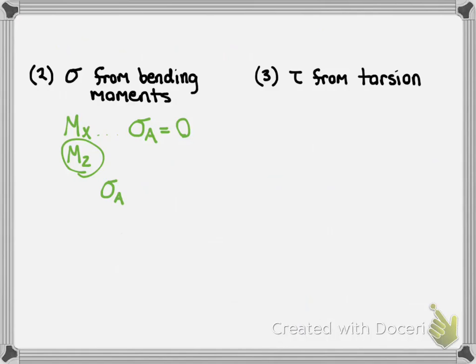This time we'll give it a superscript of 2, since it's the other component of our normal stress, and we know that's equal to Mx times y over I. Don't be fooled by this variable. It's typically written as My over I, which is why I wrote it like that, but if you look at our axes, it's actually the direction in the z-axis. Either way, we find that it's the radius of the cross-section, so that's what we'll plug in for y.